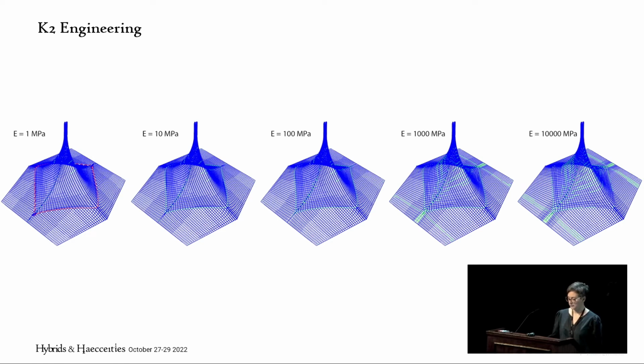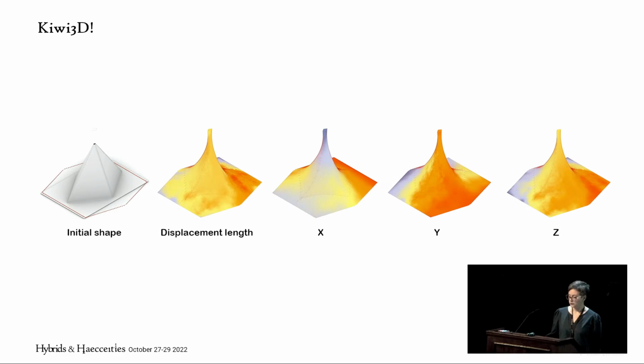during the design process. K2 Engineering for Kangaroo is a plugin developed by Cecily Brandt Olsen that contains a set of customized Kangaroo 2 Grasshopper components that can be used for calibrating goals regarding the structural performance of the tension fabric structures. We also implemented Kiwi 3D from the initial stages of form finding and analysis step.